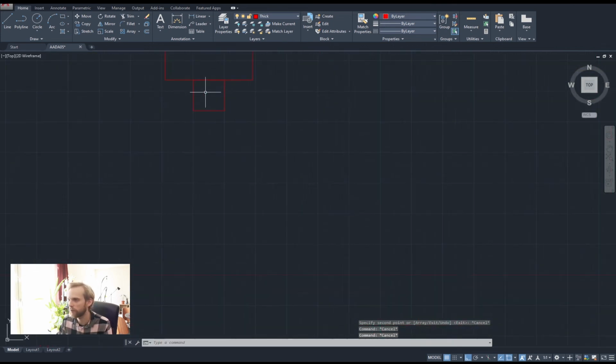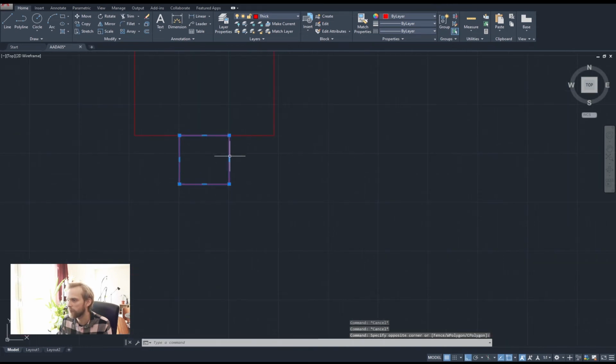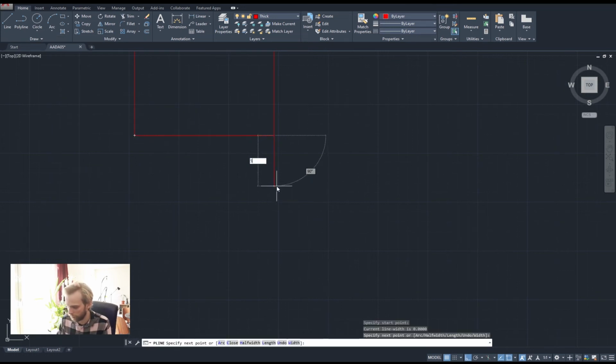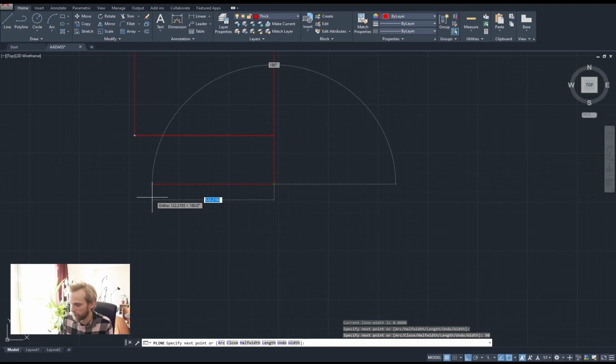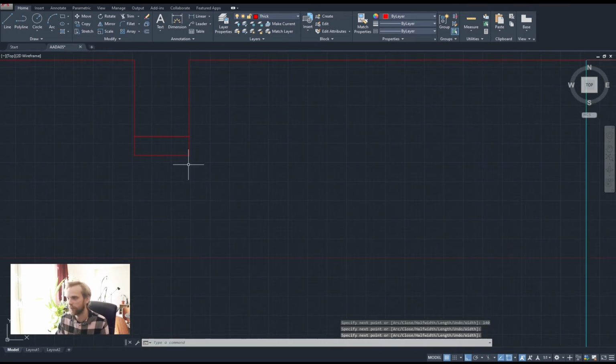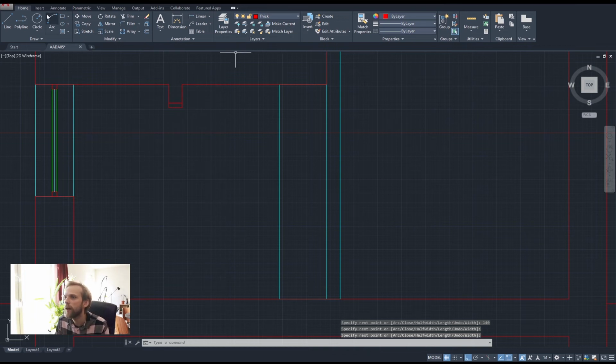That's the frame for the door, and maybe we can make it a little bit nicer as well. Yeah, let's just make it nice. So that frame is going to be all the way through, and it's going to be 5 centimeters thick and 40 centimeters wide. It's a wide frame, right? And it's going to have a door going through from the middle of it, like that.